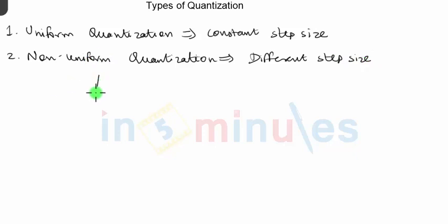For a simple reason that there might be a signal in specific amplitude range. It may happen that signal is changing, but it is taking very small changes. The values by which the signal is changing is very small. In such a case, it becomes very important to have smaller step sizes of the levels that we have in this particular range. Only with smaller step size and smaller width of the level, we will be able to assign more fixed values in this particular region where the signal is changing by small values.